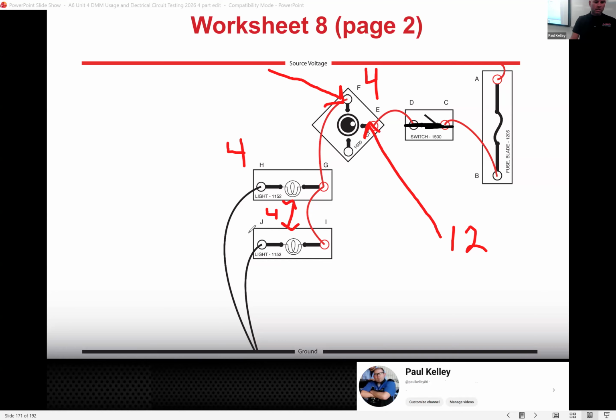This is equal to these combined. It should be 6, and that's a little bit weird, right? Because if you have 4 ohms and 4 ohms, the first part is equally strong as the second part is combined. So the first part's going to consume half. Get what I'm saying? But to actually predict this, you'd have to know what the resistance is of everything, and you'd have to do a bit of math. And that's the one time you'd actually have to do that math that we talked about. But the good news for you, never on a customer car and definitely not part of your hands-on test.